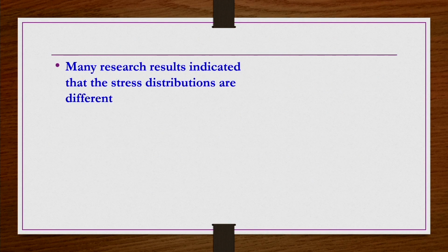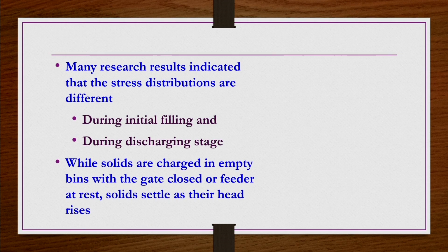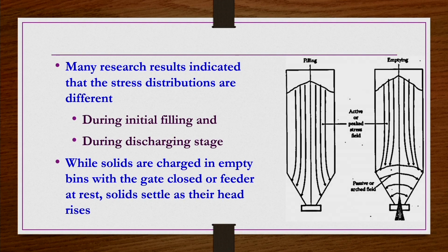Many research results indicated that the stress distributions are different both in the filling stage as well as in the discharging stage. During the initial filling and during the discharging stage, whatever the pressure is, it is going to be different, or the stress is going to be different. While solids are charged into empty bins with the gate closed or feeder at rest, solids settle as their head rises, as shown in the picture.